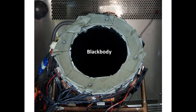So with the two independent pieces, the cap and the cone piece, we can maintain their temperatures independent of each other, and then we can collect a whole data set across a whole range of temperatures. And during the calibration procedure, we also collect the millivolt signals from the radiometers. This produces a large data set that we can then use to derive custom coefficients for all radiometers that allow us to convert the signal, which again from the previous slide was proportional to the radiation difference, to a temperature.